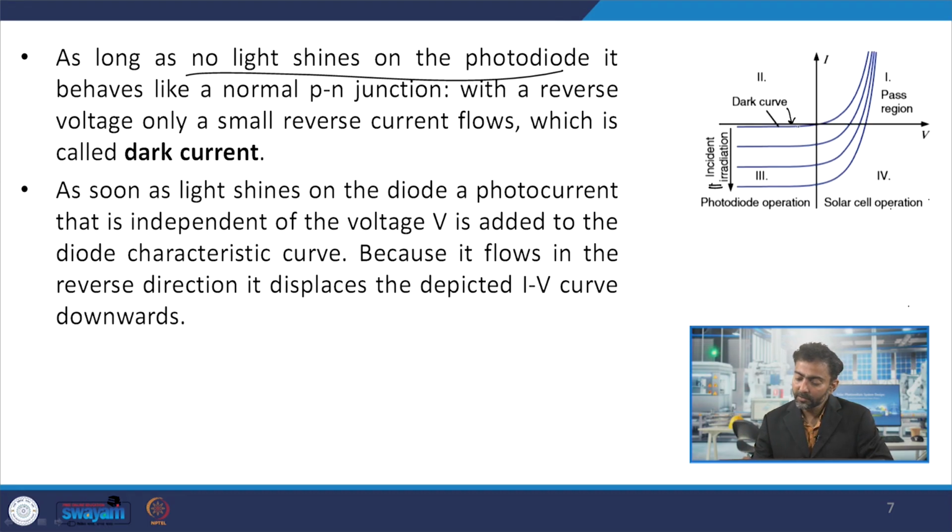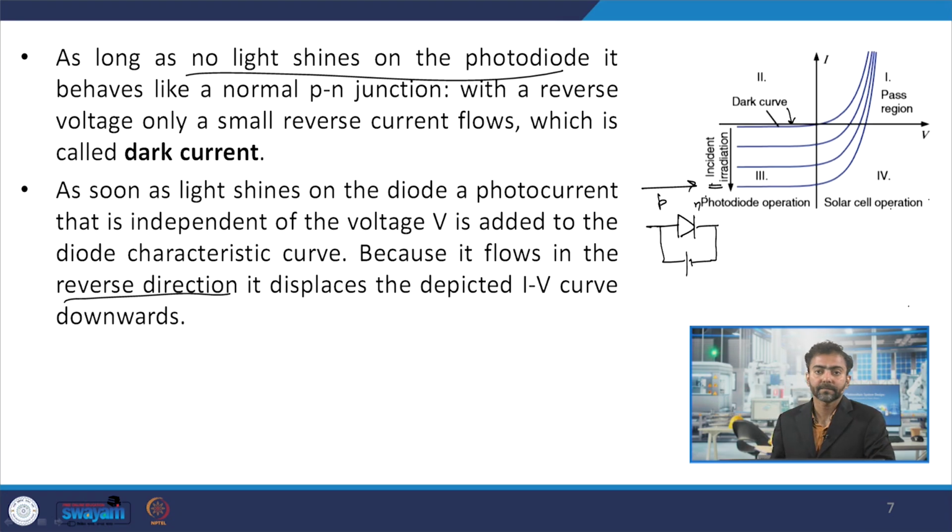So, from the first topmost graph we go to the second one. If we increase the irradiation further, we go to the third graph, or further down to the fourth graph, like that. And why are we calling it the reverse direction? Because, as we just discussed, for a diode, this is P type and this is N type, and then we have forward biasing. If I forward bias a diode, then the current goes from P to N inside the device.